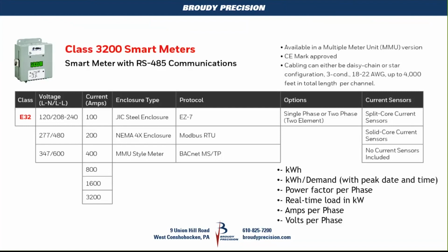We could do our information gathering through this meter into our JACE and then disseminate that through our different control systems, either controllers or pieces of equipment that are controlled via integration through BACnet or Modbus or LON or whatever. Most of the meters, okay, George is telling me that the EZ7 is still available on a couple of different meters.